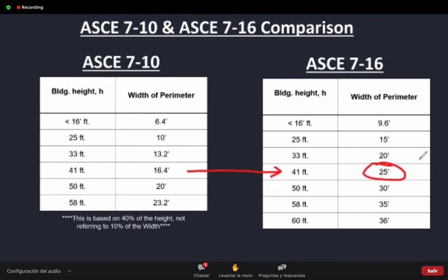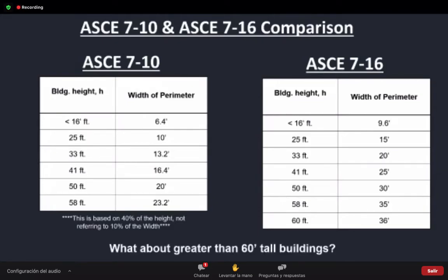So once again, guys, do not kill the messenger on this, because yes, our perimeter got way bigger. It's going to need a lot more fasteners, especially for an adhered system, right? And a lot more labor, right? And that's, once again, Wally and myself, where we were contractors, this stuff right here is a killer, right? This is where, like, oh my God, now I got to put more money in for my bid because of labor. And you guys are installers in the audience. You guys are looking at this going, holy crap. But again, we didn't come up with this. And, you know, roofs weren't blowing off. I mean, if a roof was blowing off, it was mainly from an installation issue.